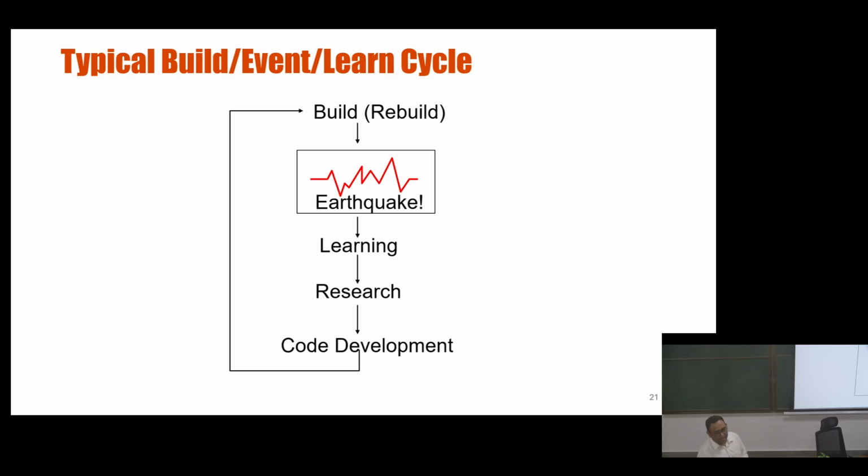That propels or catalyzes a lot of research with a lot of universities. For example, the 1994 Northridge earthquake gave rise to something called the Consortium of Universities for Research in Earthquake Engineering. If you have been part of some testing here with the cyclic testing profile, one of the cyclic testing protocols that is used predominantly in the world is called the CUREE protocol, where the amplitude rises with every cycle, or every 3 cycles.